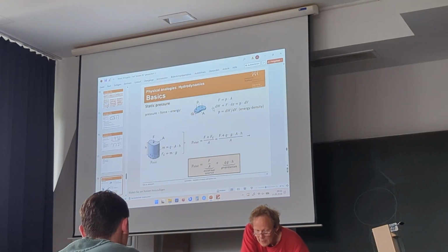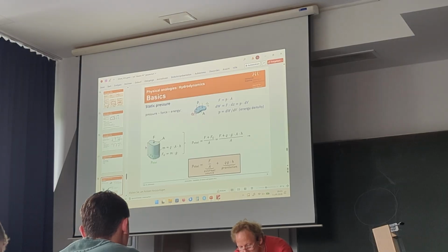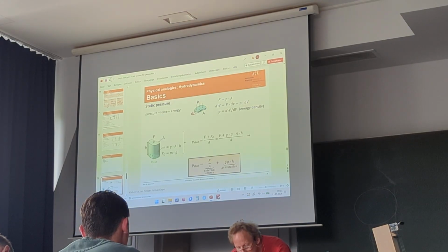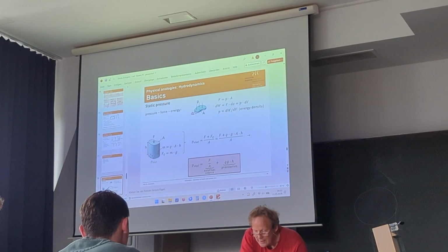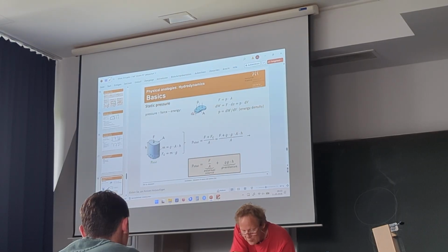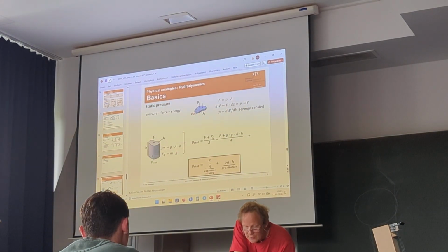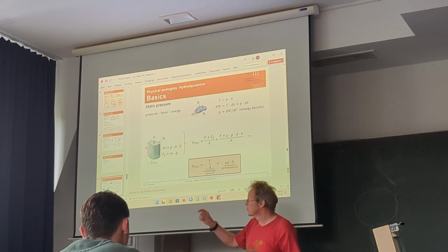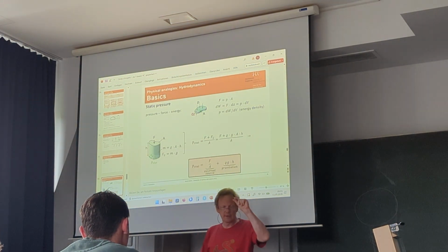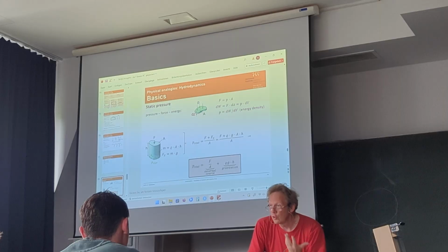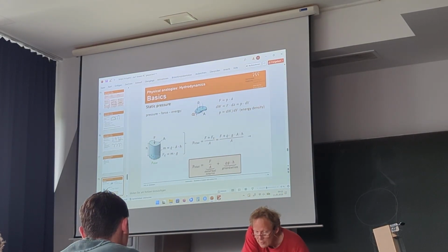And the force is the pressure multiplied with A. That means if I replace the force here with the P, we have the factor A, and A is the surface of the disk, and the surface multiplied with a small length is a small volume. So we have changed, or we have passed the volume dV.